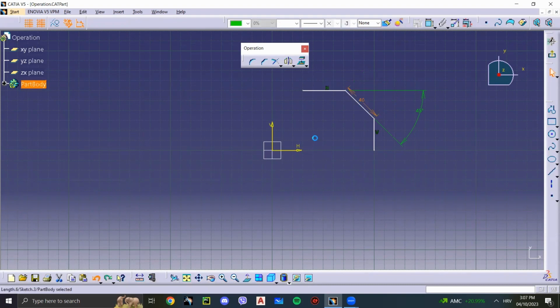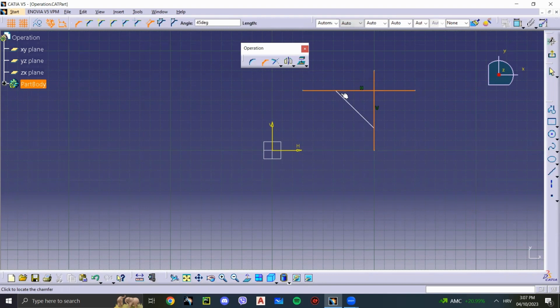Now let's Control Z this. Everything is similar in this scenario, but let me show you this. Notice the first line you pick. If you pick this one, then the second one, and then select the angle to be, let's say, 75 degrees, it's going to make, from the first point that you've chosen, the 75 degrees angle to come off it.